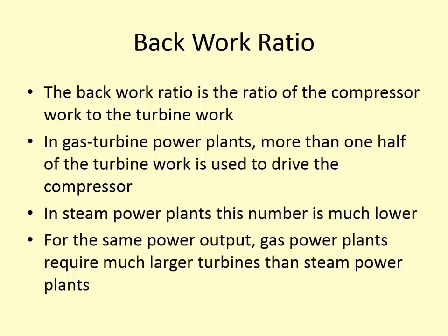So in gas turbine power plants, a significant portion of the work that they're generating has to go back to running the plant. Whereas in a steam power plant, most of what you generate is actually used for electricity, and a small portion goes back to the pump to actually pump the fluid up to the heat exchanger. So for the same power output, the gas power plant has to be bigger. So the gas power turbines are much bigger than a steam powered turbine. So these plants require larger components and generally they're more expensive.